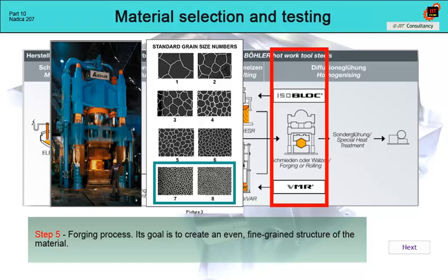The grain size is defined as the number of grains per unit area. This means that the higher the number, the finer the grain structure. This results in a greater resistance of the material to crack propagation. Because the base block from which the steel supplier supplies the individual blanks for the die casting die inserts is heterogeneous, the grain fineness in the surface areas is better than inside the block.